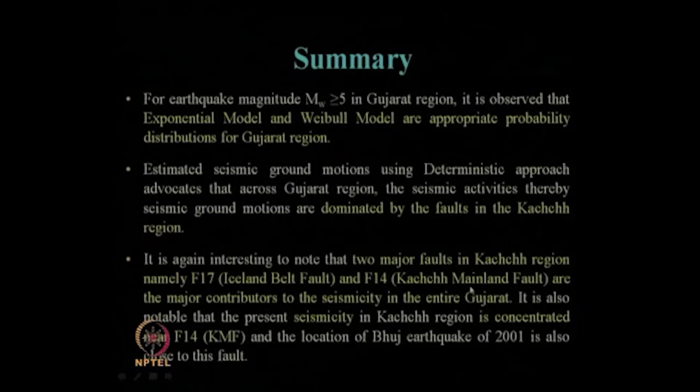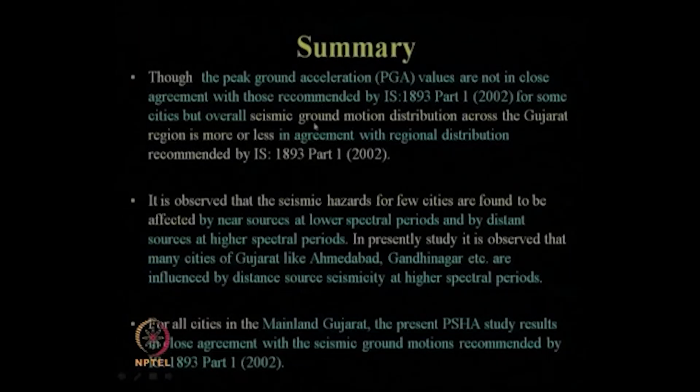For deterministic hazard, we have seen it is not necessary that only one fault will dominate. It depends on at which time period you are doing the analysis. And according to the IS code, we have seen it is in close agreement as far as MCE is concerned, but if you want to do it for another return period level, we need to do a rigorous analysis for a particular location.